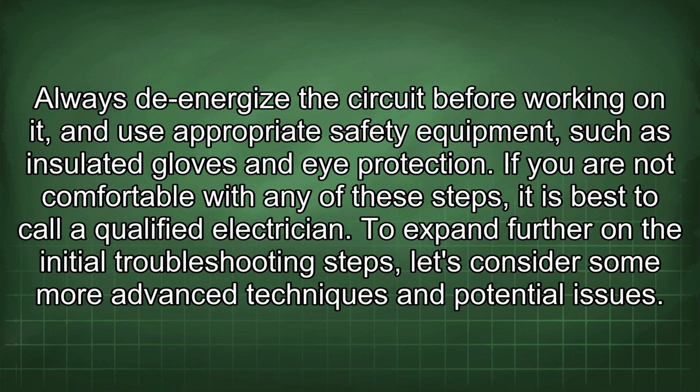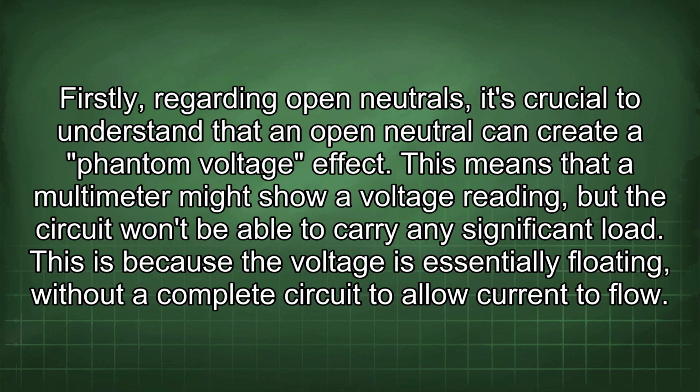To expand further on the initial troubleshooting steps, let's consider some more advanced techniques and potential issues. Firstly, regarding open neutrals, it's crucial to understand that an open neutral can create a phantom voltage effect. This means that a multimeter might show a voltage reading, but the circuit won't be able to carry any significant load. This is because the voltage is essentially floating, without a complete circuit to allow current to flow.